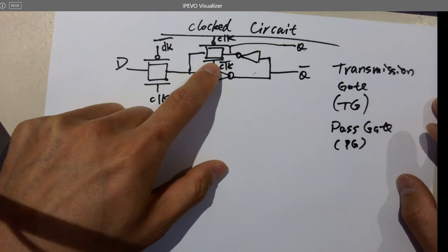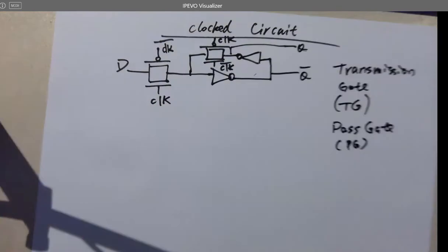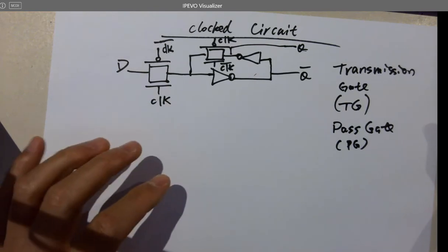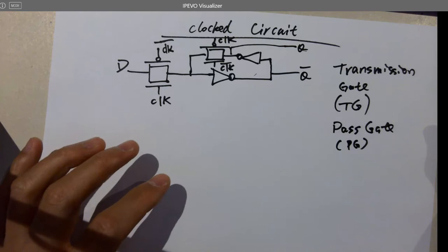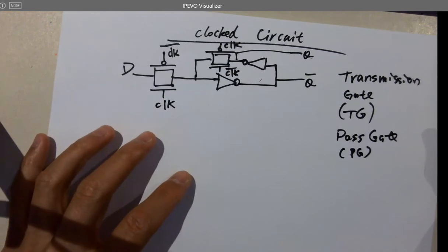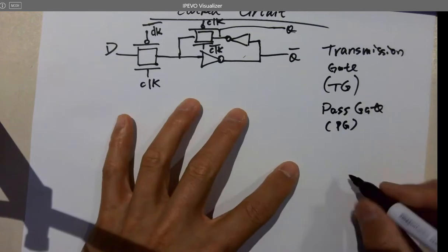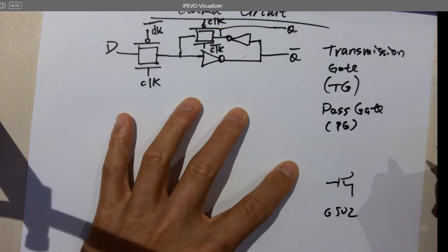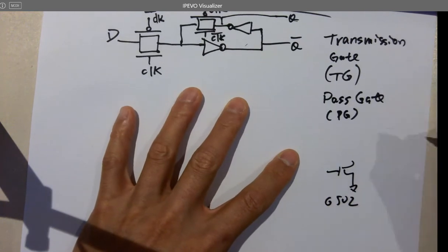and PMOS is good at passing ones. That's why we have complementary MOSFET, which is also called CMOS, right? Because we put all the PMOS stuff on the top to conduct VDD, and we put all the NMOS structure at the bottom to conduct ground. That's why it's called CMOS. We prefer using CMOS instead of just NMOS or PMOS logic. For example, the very old 6502 CPU developed in the 1970s does not have CMOS. They have NMOS logic. Can you imagine that?